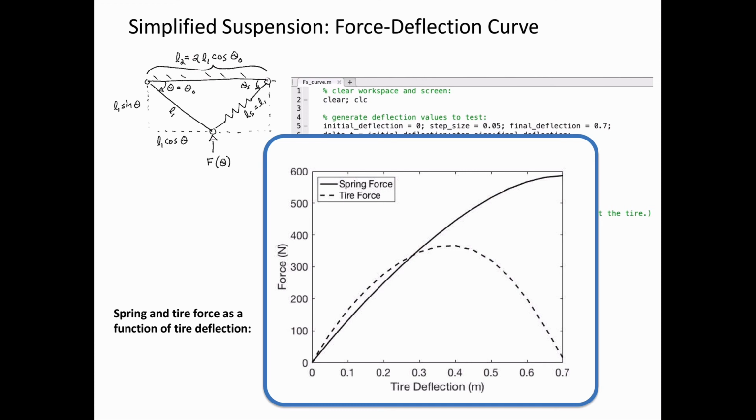So essentially what would happen if we go beyond this critical deflection limit, it's not going to require any more force to continue deflecting, moving the joint up vertically. And so it's going to be an unstable suspension. So in a mechanical system design, usually this is something that we want to avoid. We don't want to have this kind of instability that could result in a failure.